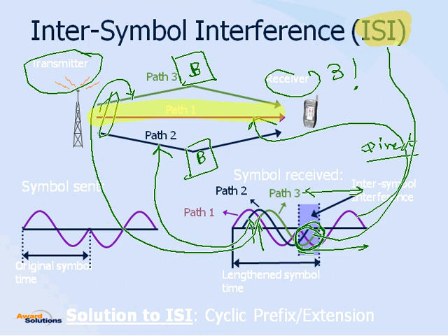And yesterday I asked you guys a question, what is the solution in SC-FDMA, and you mentioned rake receiver. So the rake receiver can resolve the multipath, and one finger of the receiver can look at one multipath, another rake finger can look at another multipath, and in that case we do not need to fight multipaths, we combine them. Okay. We welcome them. As long as you have enough number of fingers, you are okay.